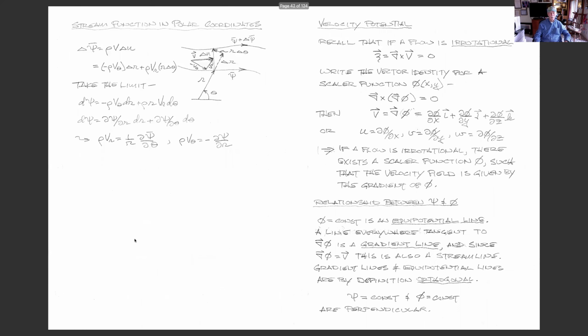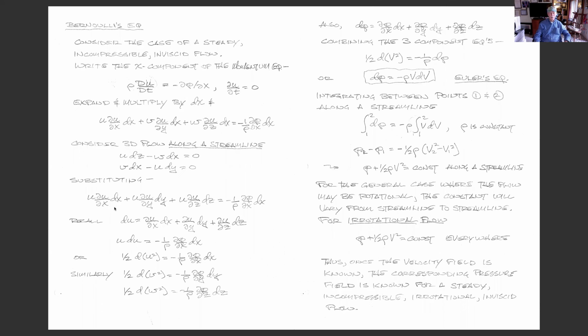We've got this done, and if I can factor out du out of here, it just reduces to u du equals minus 1 over rho partial p with respect to x dx. This is just mostly algebraic manipulation. Or I can write this as 1/2 du squared is equal to this.